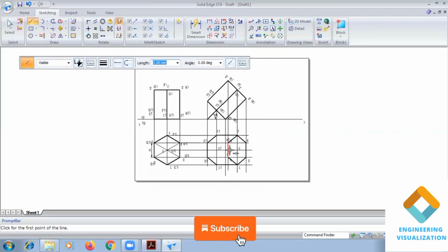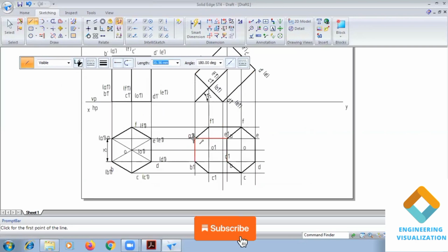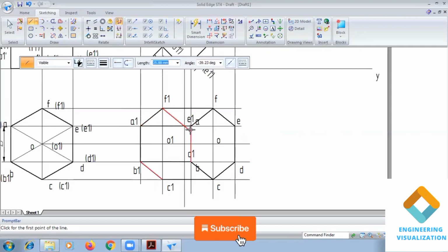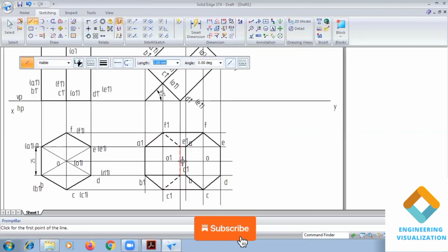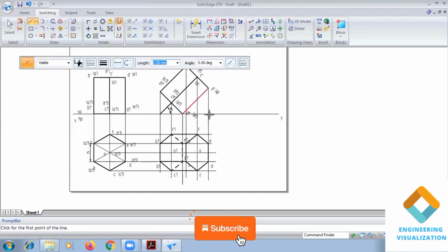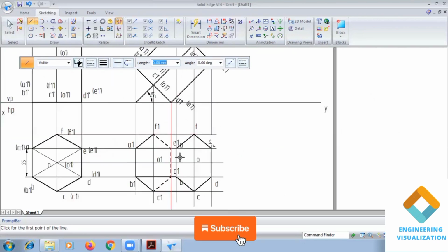And this rectangular face is also visible. This hexagonal base is not visible from the top view, so it is drawn with a dashed line. Here, this slanted rectangular edge is also not visible. You can show part of the line here from here to here.